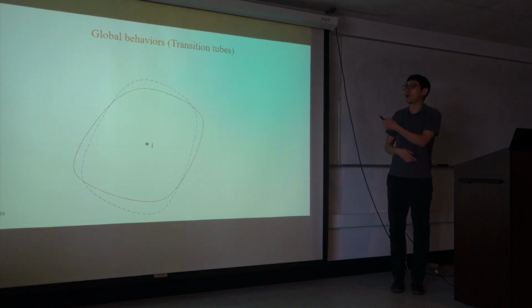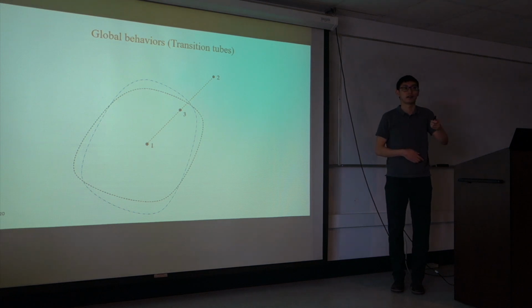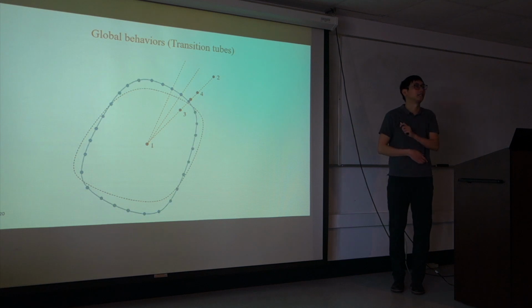For example, I select one point inside of the boundary, and then select one direction, and select one point outside of the boundary. I can select their middle point and integrate the nonlinear system forward in time, and I can know this is a transit orbit. So I can select point 3 as the inner point, and then select the middle point again and again. Finally, I can obtain the boundary along this direction, and I can select another direction and find the boundary. So finally, I can obtain the boundary for the nonlinear case.